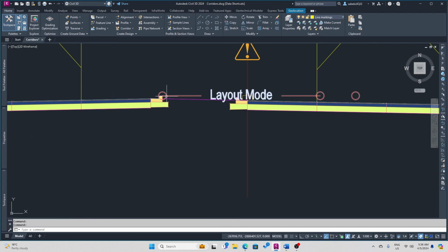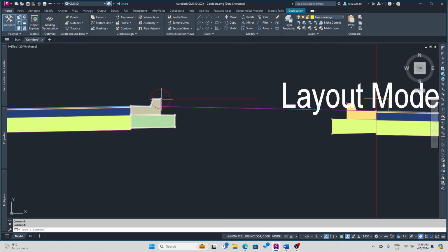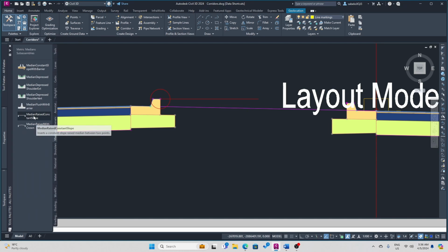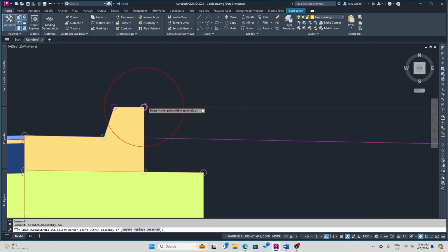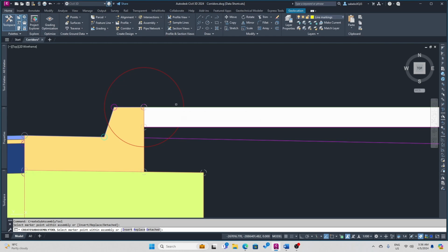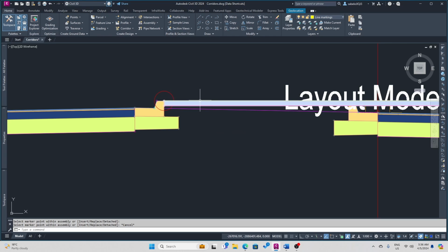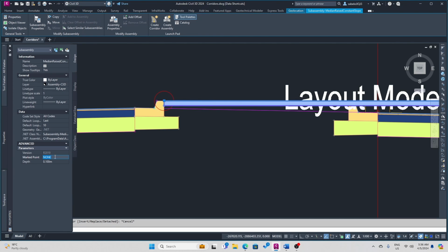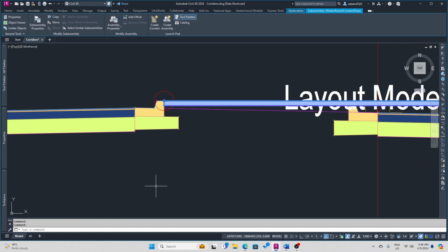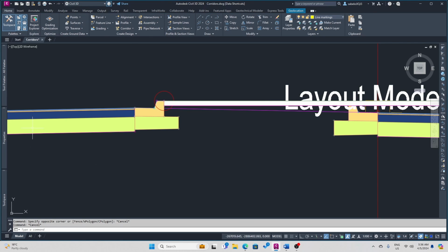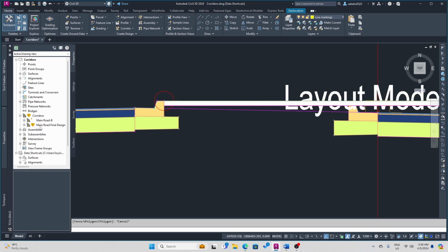We now want to connect this space between the cabs with a median. So for that, we're gonna come here and then we can use this raised constant slope, or we use the median raised with a crown. But I think in this case, we're just gonna use that. And we're gonna insert it there. We will leave it with that name. If we come to the properties of that, you can see that it's not targeting any mark point, and we want it to target the median. Let's see, yes, it's still targeting the median. Okay, we're gonna now need to just rebuild the corridor.